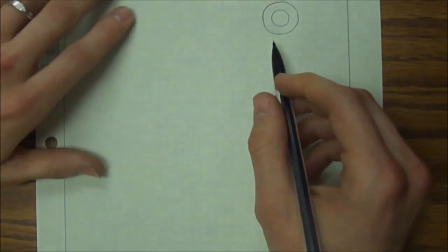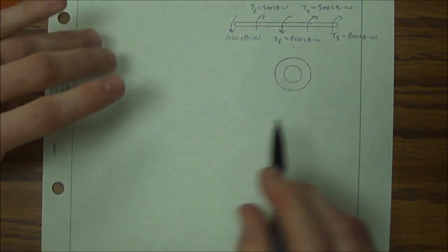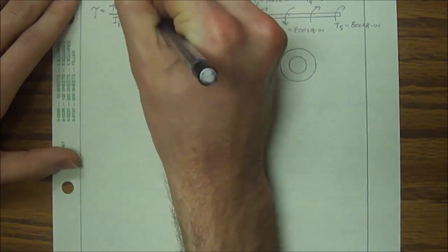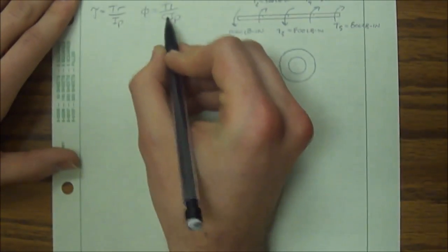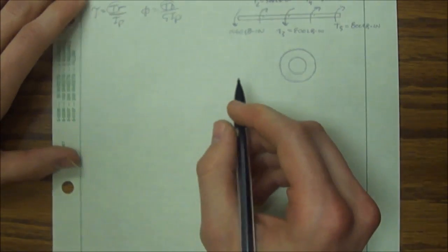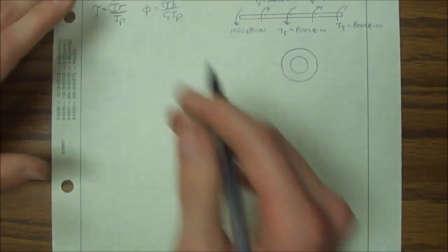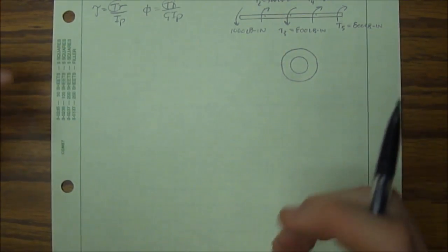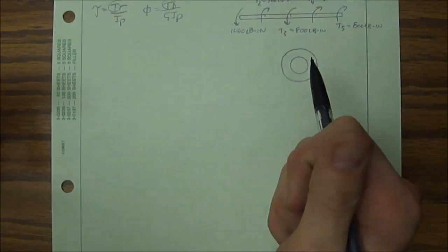Okay, I like this problem just because it hits a point home, something that is super important with this equation, and for that matter, this equation too. So for both these equations, we have torque. And something that is super important is that this torque is for, we were just looking at uniform bars. It is not the applied loads, is not the applied torque. It is the internal torque that matters.